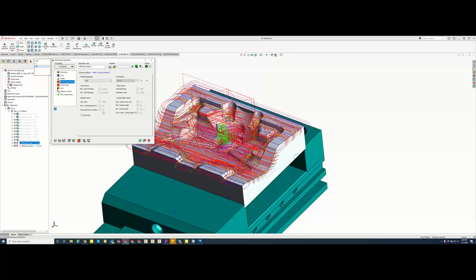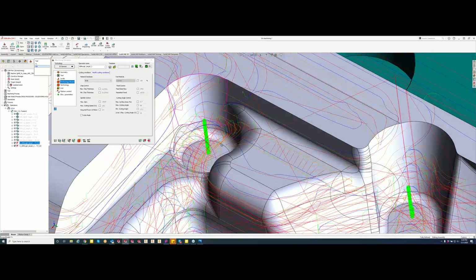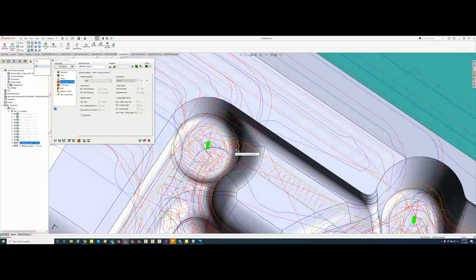So getting back to the horsepower, I know Brendan was talking about how iMachining is going to increase your tool life and decrease your cycle time. But one thing to remember, when we're using iMachining, we are utilizing high feed movements. What I mean by that is when that tool goes to reposition into another area, it is using a G01 with a high feed move. So for those of you that switch back and forth between a G00 and a G01, you always have that moment where the machine has that quick little stutter, and then it keeps going, where with 2D iMachining or 3D iMachining, it's going to stay in that constant G01 move, keeping the machine from jerking. As well, if we get into these tight corners right here, where normally you would get a chatter, you won't get that anymore just because we're not over engaging the end mill.